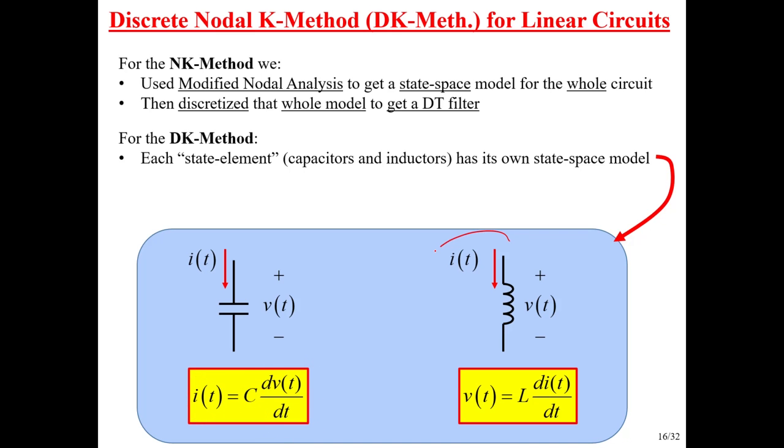And similarly, we take as the state variable for the inductor its current. So here's the derivative of that. And if we swung that over to the other side, viewing this as the input to the model, we have a state model. Now, the thing that's missing is how the current state goes into the derivative of the current state. So in other words, there's no I over here and there's no V over here. But nonetheless, it's still a state model. It meets the conditions. It's just that the A matrix in both cases is 0. So kind of a special case.